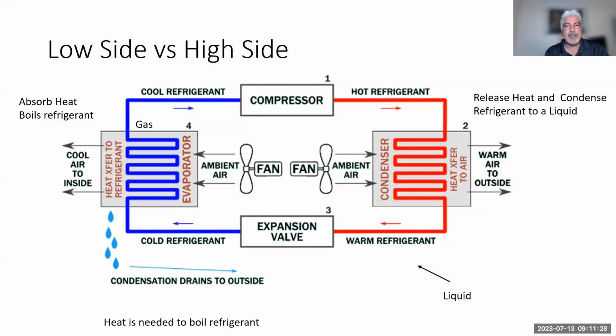So what a lot of us would do is look at the evaporator inlet and outlet and see what the temperature variances are. Even though it's working with 1.5 pounds, even though it's supposed to take 2 pounds, it'll still work decently, but you just lost the ability to use the full capacity of that evaporator. If I have access to that evaporator, like some have a bottom tray which you can remove, and you could see the evaporator on those models, not all models, you could actually use an infrared temperature gun. You could see where the restriction might be.